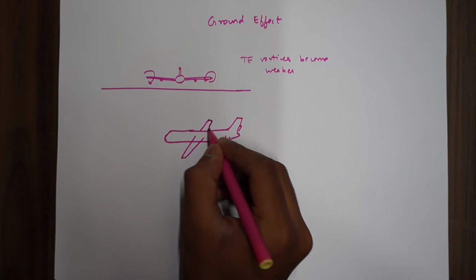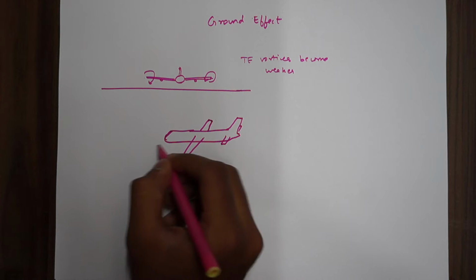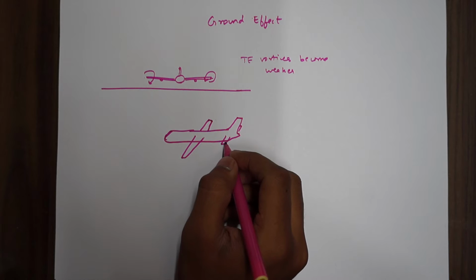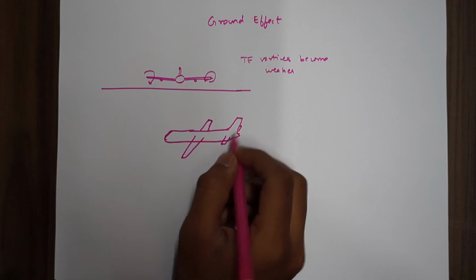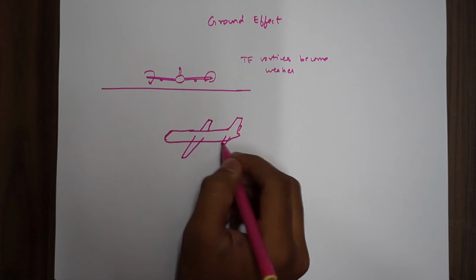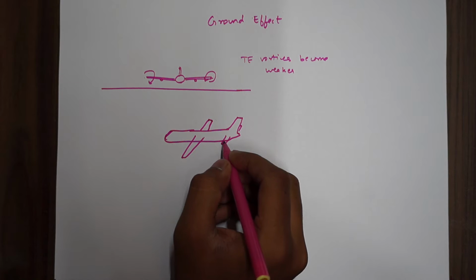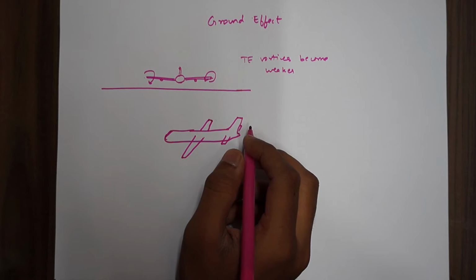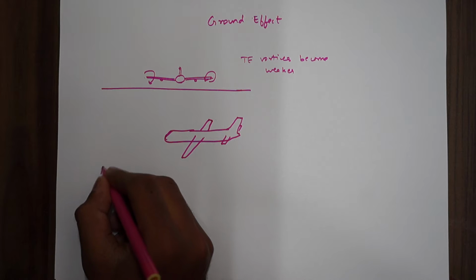Relative airflow, we know, is the airflow hitting the aerofoil, but the tail plane does not get relative airflow, because it has been affected by the aircraft itself. So this is called effective airflow, and the angle between the chord line and the effective airflow is called the effective angle of attack. I'll write down a few sentences so that it's clear.